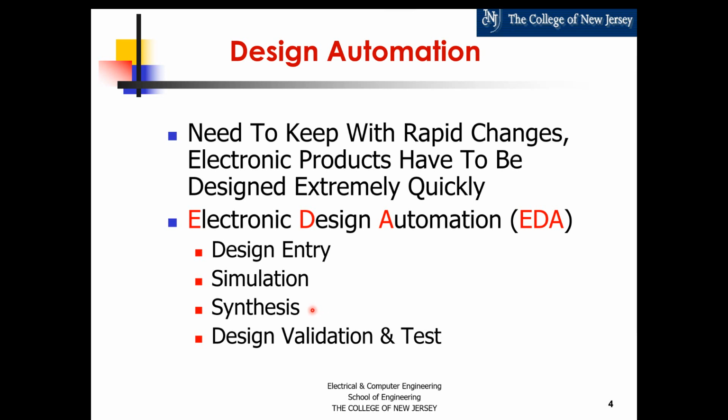But to have a synthesis tool do its job, for example, synthesize a state machine, instead of you having to hook up the flip-flops and the gates and things like that, you need to put something in. You need to tell it what you want. That's where a hardware description language like Verilog comes in. You're going to be describing the hardware that you want so that the tool can do the synthesis, which avoids you having to do schematics. That's what we want, because you cannot do schematics when you have 20 million or 50 million gates on a chip.